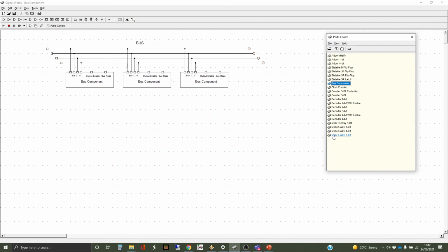Even though I said the compromise is speed, because of the physical proximity, and in terms of the simulation that we've got here, using the simulator without a bus would probably grind the simulator to a halt. In fact, it means you can run things faster. You end up with a faster clock speed, and things do actually go faster when you use buses than if you use multiplexers all over the place. So you need to pick and choose which strategy you're using for the different parts of your CPU.